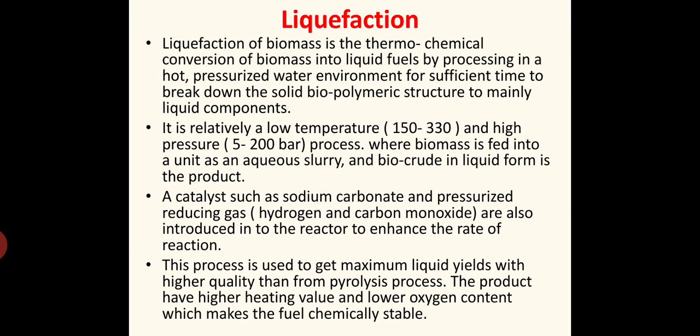Inside the reactor, the temperature will be around 150 to 300 degrees Celsius, and the pressure will be from 5 to 200 bar. So, the chemical reaction happens within this reactor, and finally we obtain the liquid components. Actually, vapors are formed, and on condensation of this vapor we produce the liquid fuel. So, liquefaction of biomass is the thermochemical conversion of biomass into liquid fuels by processing in a hot pressurized water environment. That is what is called a reactor.